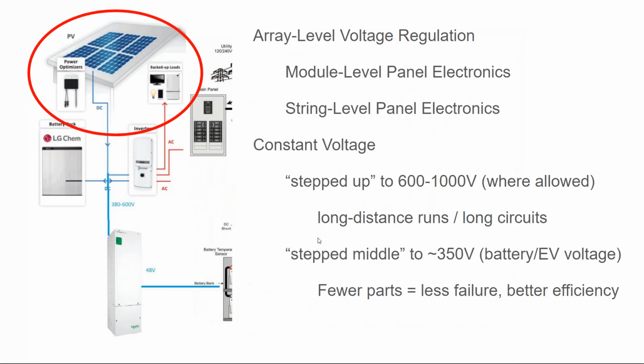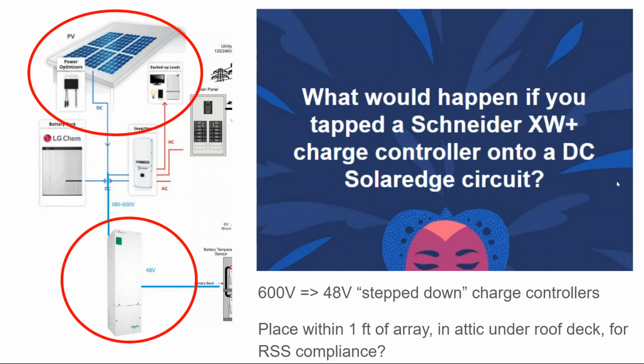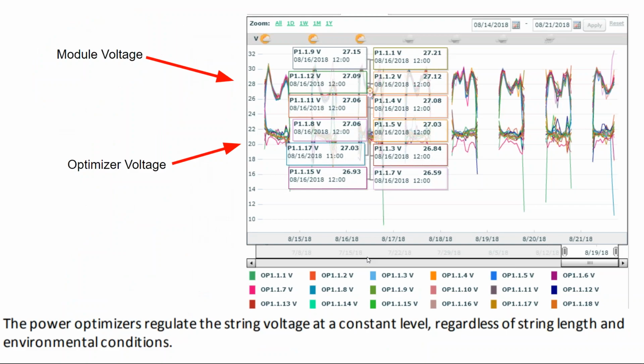So that's what these next slides go through, which is basically saying that, even though the inverter manufacturers tell you, no, this does not work, indeed, you can combine multiple battery chemistries together on the same circuit.